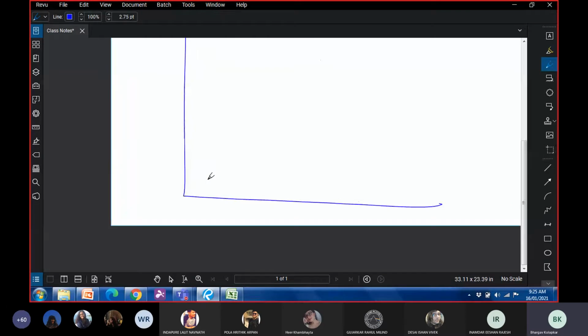Now, when we look at the stress strain curve for different grades of concrete, for example an M20 curve might look something like this. An M40 curve might look something like this. An M60 curve might look something like this. So right from the origin, the stress strain curve for concrete is dependent on the grade of concrete.